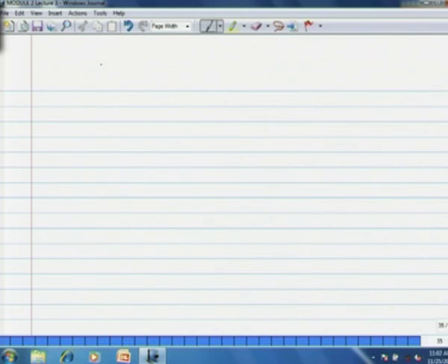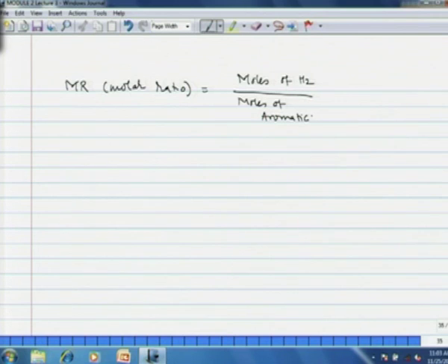So, let us say that MR denotes molar ratio, the moles of hydrogen to the moles of aromatics. I am using the word aromatics instead of toluene because we may also consider in the later discussion recycling of diphenyl to the reactor system. So, the total aromatics is toluene plus diphenyl in case diphenyl is recycled, or only toluene if diphenyl is taken out as a side product.